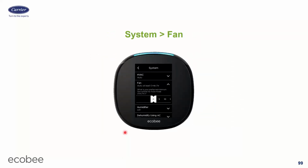Fan, the default here is 0 minutes. So there are two different places the fan control gets set up, and they work together but differently. In the schedules of the stat, home, away, sleep, when you configure those, you tell it if you want the fan to be on, which means it runs the whole time, or auto, which means it turns on with a heat or cooling call. So for home, you'll probably put it on and let it run the fan. Whereas in away, you definitely wouldn't do that because you're not home, so you put it in auto and let it do its thing, just like a normal thermostat would do. Then in addition to that, and unrelated to that, there's this fan timer.